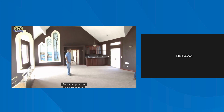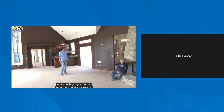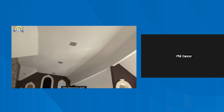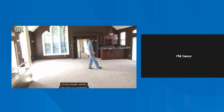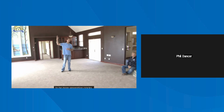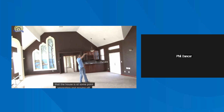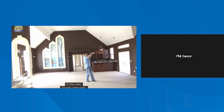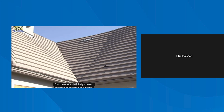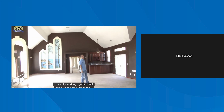So we're up on the main floor now, and the first thing that's glaring to me is the large crack that's running up this wall here, over the ceiling, and then back down the adjoining wall. There's also a high point here in the carpet, which you probably can't see on camera. These are going to be separation cracks, indicating that the house is at some point separating and moving off. In this case, both sides, but sometimes it's one side of the house going. These are definitely caused by separation of a house working against itself and away from itself.